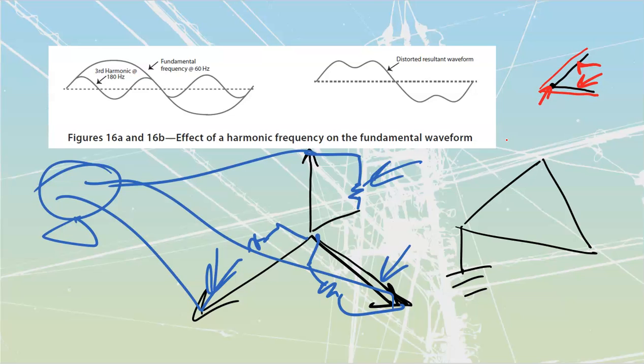We will get power quality issues from a number of other things as well, where they're going to go through a few other last ones. Things like loose electrical connections. If we get cold flow under the aluminum, where it heats up and then flows out from underneath points of pressure, that's why you're supposed to be retorquing your services. Faulty installations, particularly where you have ground loops, where you've got the neutral connected to ground in more than one location. Large motor startups, which are going to disturb things.